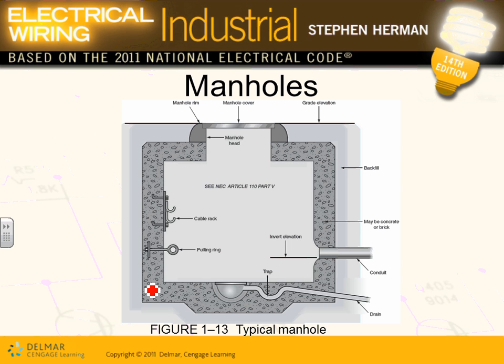Here's the manhole. When we use a manhole, guys, if you go downtown Minneapolis, it's full of manholes. A manhole is a place where a man or a woman can walk in and work on these. So look at them. Here's the invert. Remember that bottom, we said invert elevation? Here are my conduits and wires coming in, guys. Here's cable racking. You can rack your cables here. Pulling, you can anchor to pull. You have a rim here and a cover.